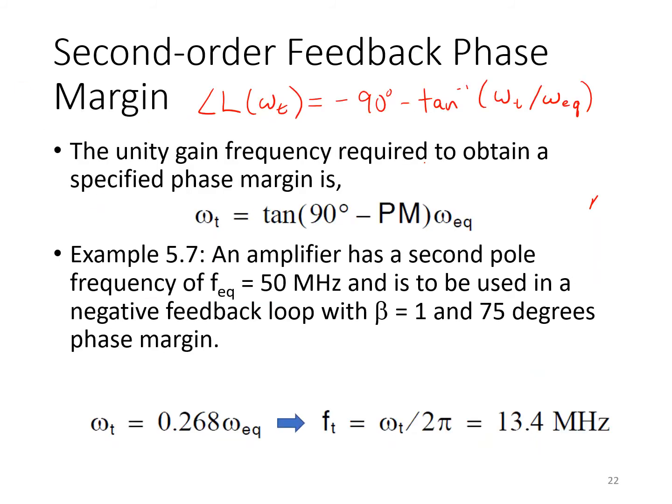And that's exactly what we do here. We just evaluate that expression for the phase response of L at omega T, and we rearrange and recognize that the phase margin is just the value of the phase of L evaluated at omega T minus negative 180 degrees.